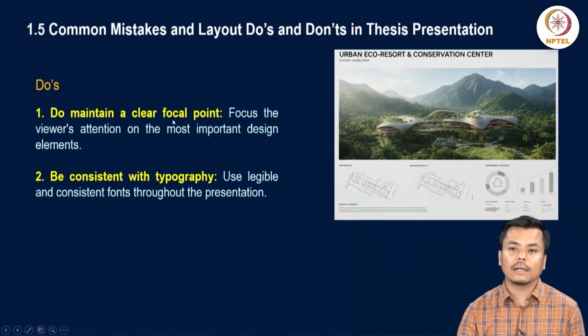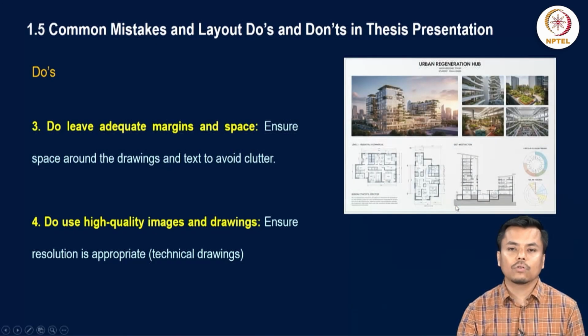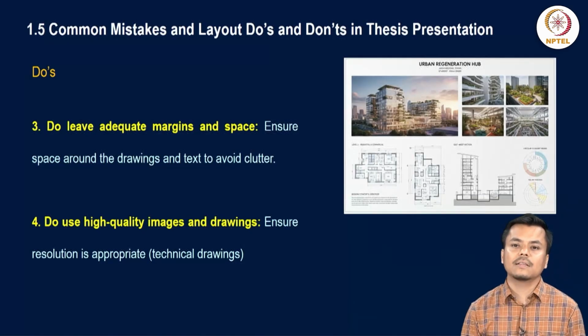Let us now look into some important do's that you can follow in your sheet preparation. Do maintain a clear focal point, focus the viewer's attention on the most important design elements. Be consistent with typography, use a similar font across the sheet so that there is uniformity in the font style. Also do leave adequate margins and space, so that it avoids clutter in your drawing. Do use high quality images and drawings so that they don't pixelate when printed, and the details about the technical drawings are communicated very clearly.